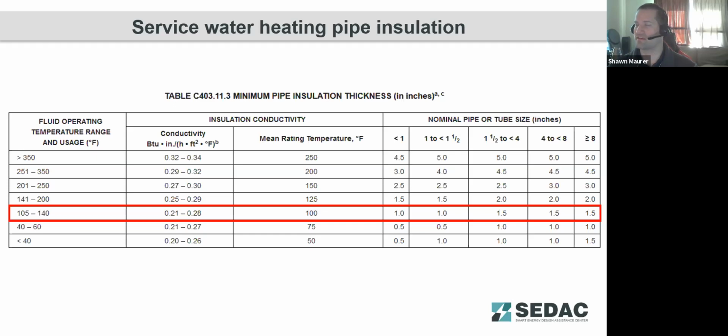There's a lot of heat loss that comes from those circulation systems, and a slight increase in that insulation beyond the minimum Energy Code requirements can result in a lot of energy savings for the client down the road, as those circulating systems are essentially just little hot water pipe radiators in the walls of the building. So something to look at, the trade-offs, long-term energy costs versus that upfront insulation cost for the client.